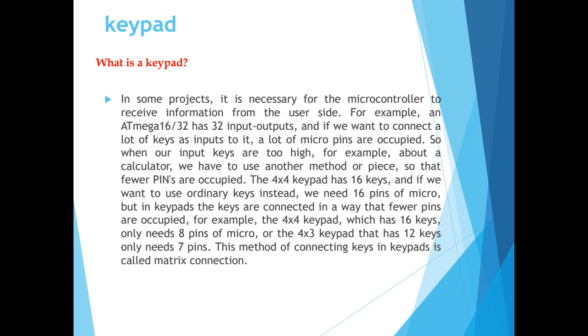Actually, why are we using keypads? In some projects, it is necessary for a microcontroller to receive information from the user side, okay? So, for example, the Mega 16 or 32 includes 32 input-output pins. Why does the Mega 32 or 16 include 32 input-output pins? Because it includes 4 ports. Each port includes 8 pins. 8 times 4 is equal to 32.